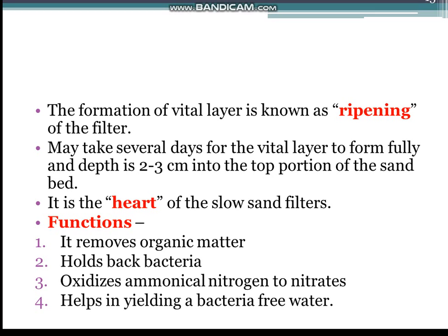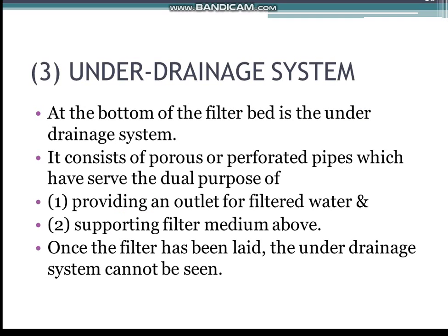It may take several days for the vital layer to form fully, and when fully formed, it extends 2 to 3 centimeters into the top portion of the sand bed. The vital layer is the heart of the slow sand filter. It removes organic matter, holds back bacteria, and oxidizes ammoniacal nitrogen into nitrate, helping to yield bacteria-free water. Until the vital layer is fully formed, the first few days' filtrate is usually run to waste.